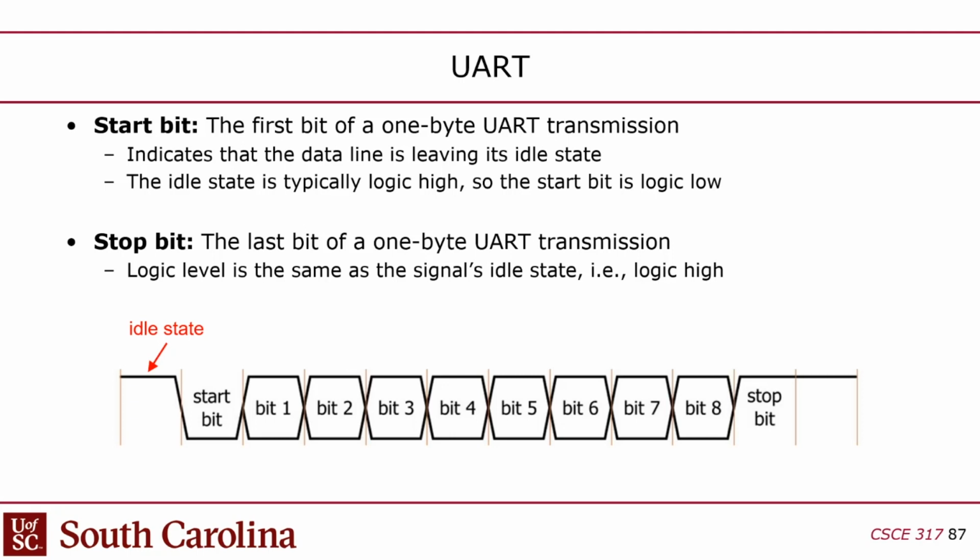The other thing with UART is the bits come in least significant to most significant, so they come in backwards order. Unlike SPI and I2C, it's usually most significant to least significant. Although with SPI you can do it the other way. With I2C you can't, because that's part of the I2C standard.